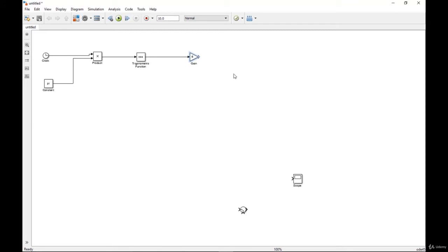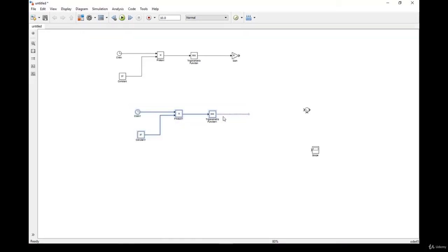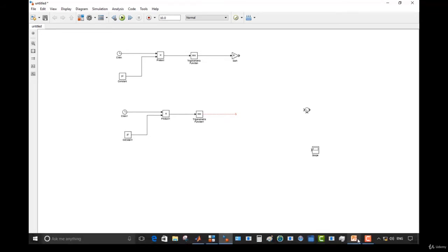In Simulink, we have both sinus and cosine functions, so we can divide them and get the cotangent. I get a copy from this part and paste it here. Then I should set the amount of cotangent based on the main equation here too.